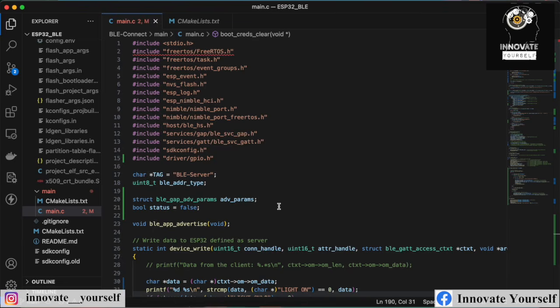So basically now we are gonna start with the coding, and in the coding part we will be covering setting up your Wi-Fi. We have two modes available in the ESP32. That is, we can connect your Wi-Fi in the STA mode or AP mode, or there is a third mode as well in which we can use both of them at the same time.